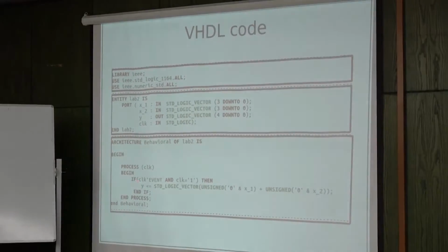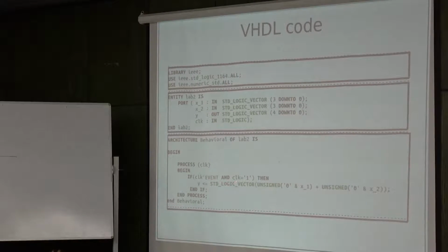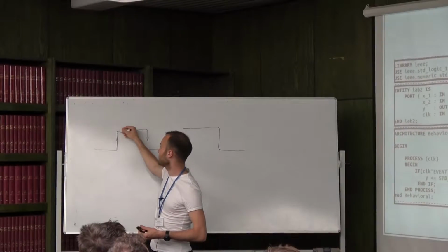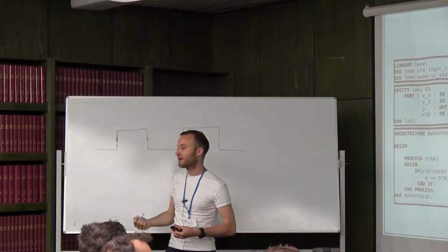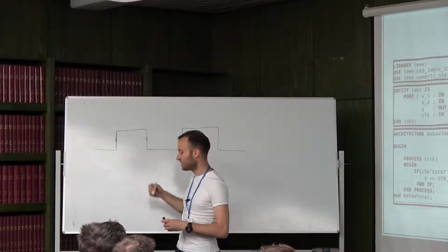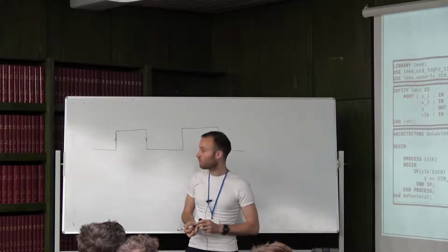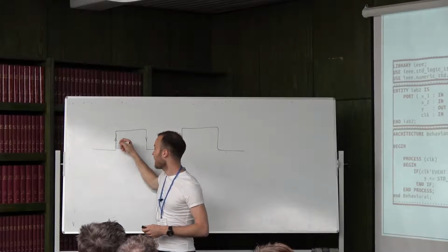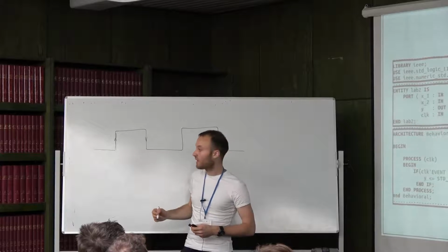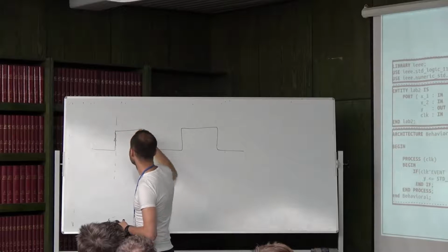So once there is a change, we check what is the current state of the circuit. If something happened and the current value is 1, that means that there was a rising edge. If the change happens and the current value is 0, then there was a falling edge. Since we are looking for logic 1, our circuit is synchronized based on the rising edge.